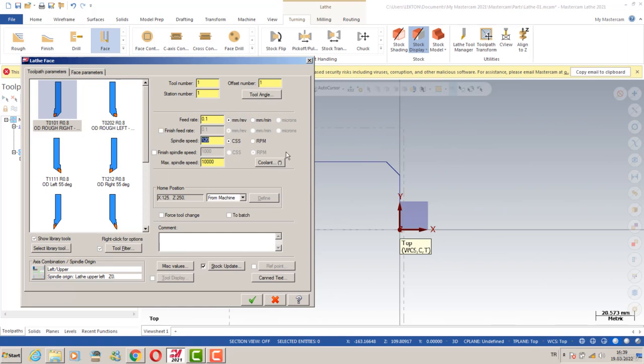So that's why if you use constant cutting speed position here, it means that we also need to write here maximum spindle speed. Otherwise, we can start from here. This is maybe the 600. We're gonna reach here 1000, 2000, 4000 and 8000. This is my maximum spindle speed, our machine. And then it means that we're gonna reach maybe 10,000 if it is possible for your CNC, of course.